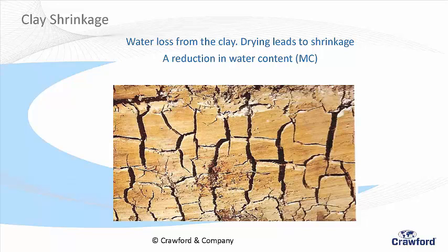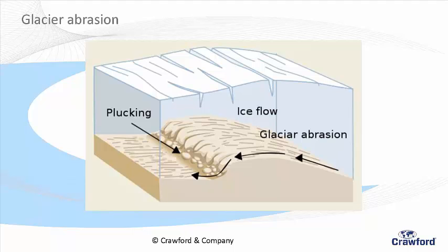If you get desiccated clay, here's a lump of desiccated clay. That's about 1,200 kilopascals. It's like concrete. And if you pour water on that, it will not absorb. So fast rainfall, even like 3 or 4 hours of rainfall, will not rehydrate that clay. It will run off. You need persistent long-term rain to rehydrate clay. Okay? Cuboidal cracking, they describe it as. Okay? And they call it clay glacial deposits.